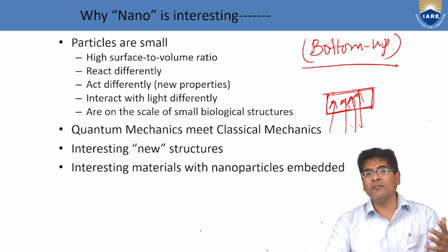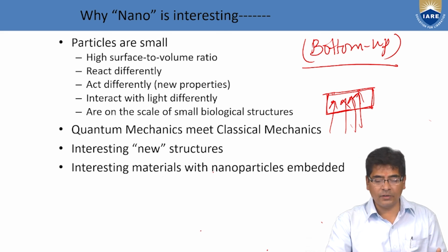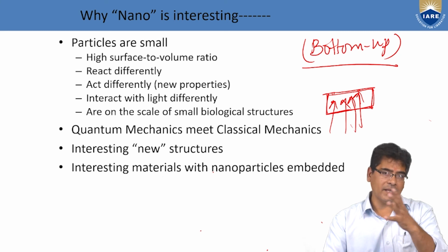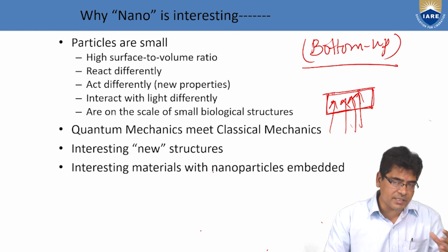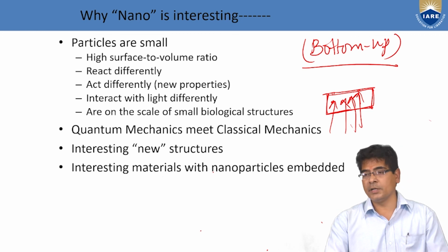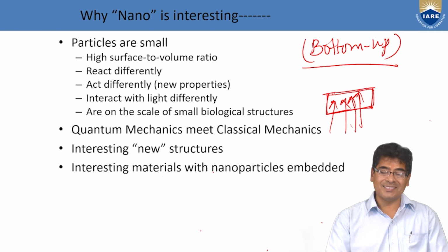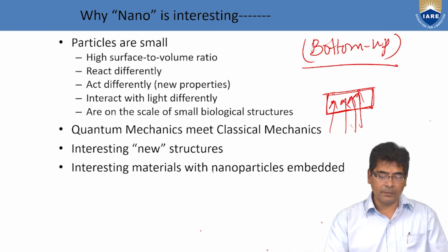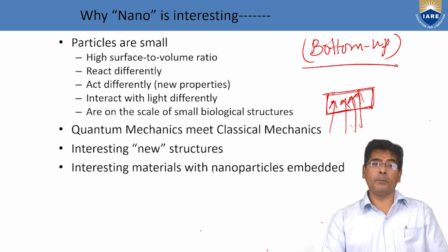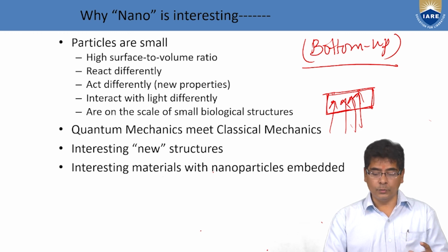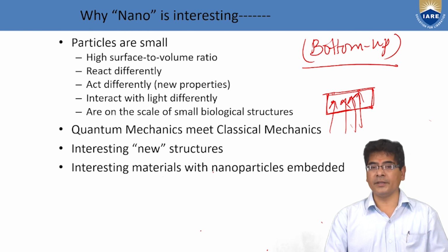All the reactive physical vapor deposition techniques have certain steps. It is a method of depositing material in combination with an active gas such as nitrogen, oxygen, or methane. There is a bombardment of plasma on the substrate to ensure a dense hard coating.